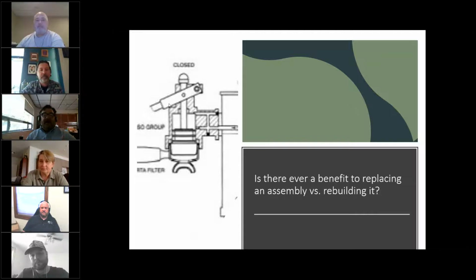It's like, well, I replaced the contactor and that just worked fine. I can tell you about 20 jobs we went back after we replaced the contactor and then the pressure stack fails, or something else along the system. So what's important about what Rachel's saying is you have to check the whole system. Replacing a part really quickly, even in the case of steam valves, isn't really work, because what's in that system is causing it. I mean, replacing a steam valve, well, it's caked with milk. Well, is there a vacuum leak somewhere? So Caleb, what are your thoughts?